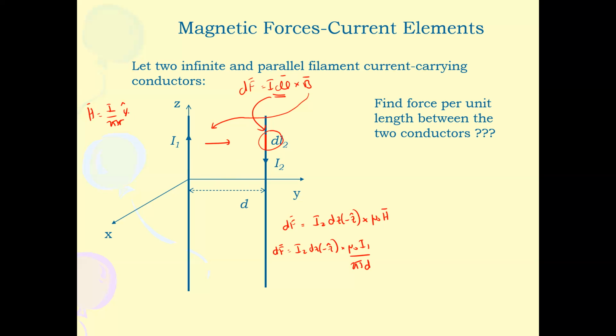In terms of the field direction, the phi direction can be written as the current direction cross R, so L cross R. L is the positive z direction, because your I1 is directed towards positive z, and R basically will be the y direction. So z cross y will give us negative x direction. That will be the substitution for the phi vector of the H field just now.